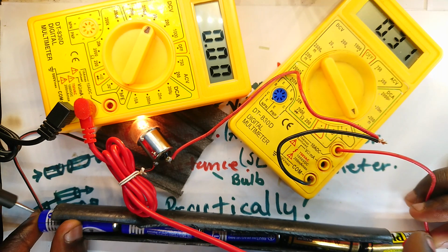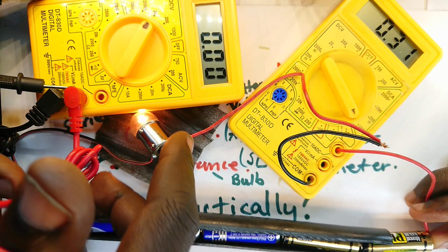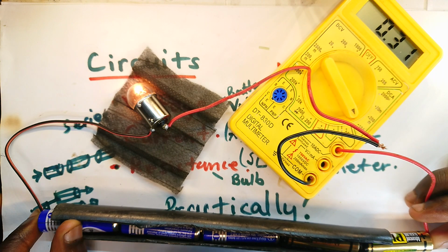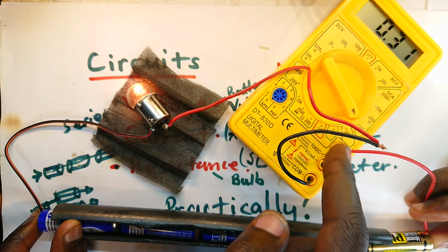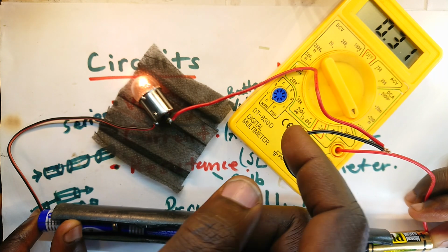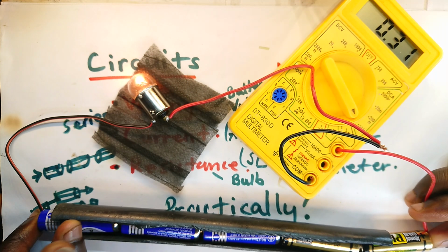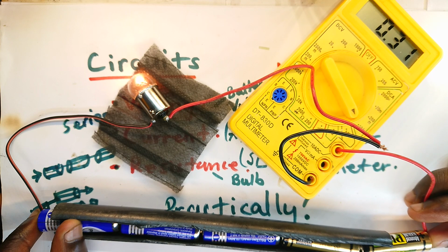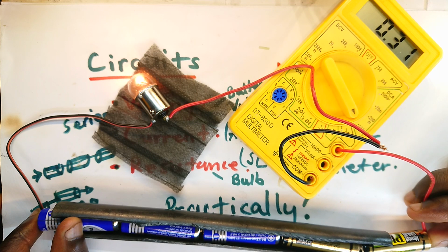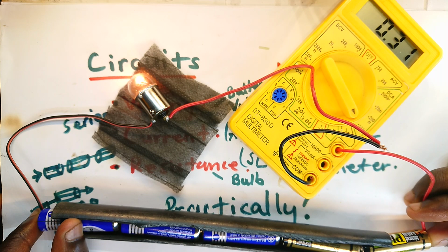I have a question. And then the ammeter has to be in series. In series, in the sense that current comes, passes through the ammeter, and then continues to the bulb, this way. Yeah, you can ask. Yeah, there is no energy gained or lost here in the multimeter? It is very tiny. The multimeter doesn't consume much. You may find it is consuming 0.00 something milliamperes.